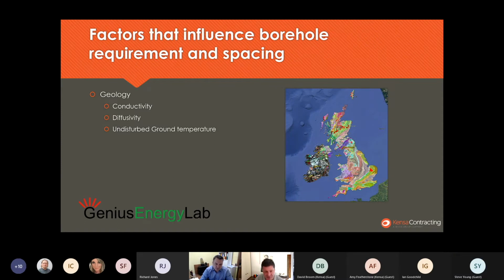So that's the geology. Probably with geology there, Chris, it's worth adding the most commonly made mistake that I see when people try to use lookup tables and the BGS geology website to do their own rule of thumb designs for sizing ground loops. They see the bedrock geology and assume it's that going all the way down, whereas it can be only a metre thick. Yep. Until you get to the next layer.